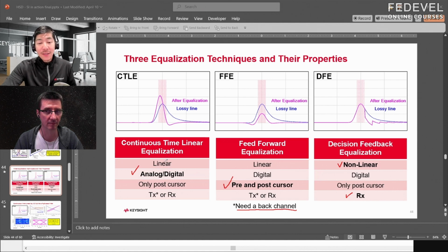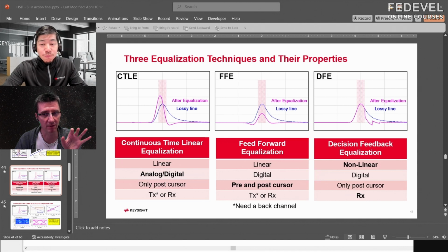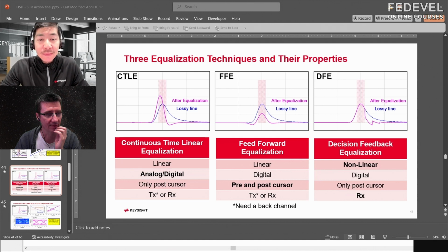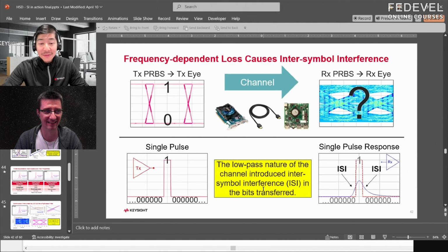and configure the equalization accordingly. Before we continue, I remember when I was creating the previous video on this topic, one of the things that was very interesting was this equalization. Sometimes it may need to consider also the previous bits, because the signal can be influenced by the bits which were running through the channel before. That was interesting. Ooh, that's exactly what we call inter-symbol interference.